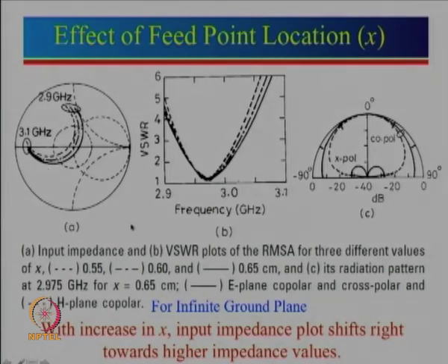But for this particular feed point, if you look at it, then what we can see is that it is almost passing through the diameter of the VSWR equal to 2 circle, and that is where it is more important, and that is why this one gives a better bandwidth. So, in fact, I would like to tell my audience that it is not always important that you design antenna for exactly 50 ohm. In fact, most of the time I design antenna for 55 ohm or 60 ohm impedance, which will be something like this plot here, and that will give me a slightly larger bandwidth.